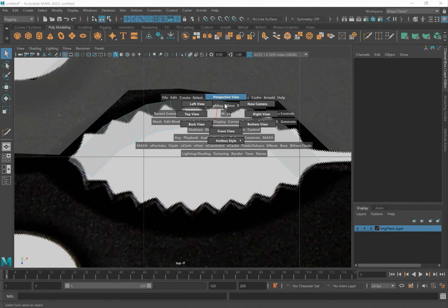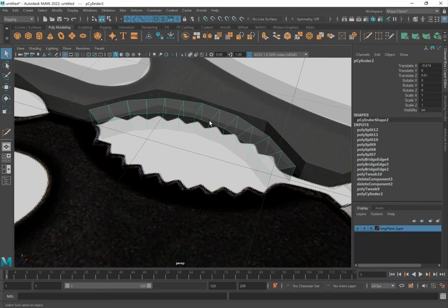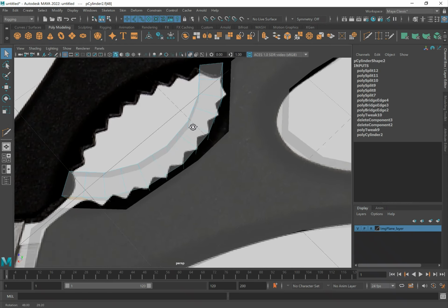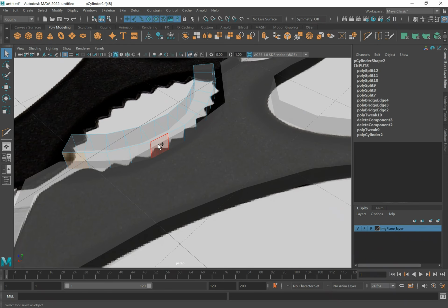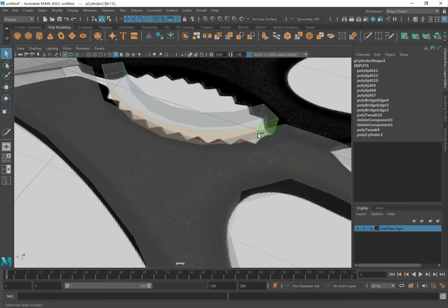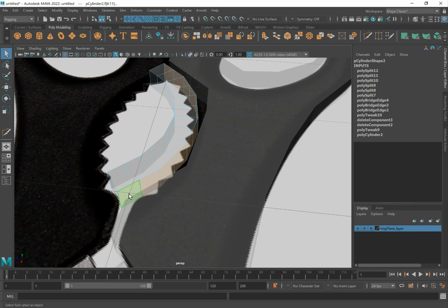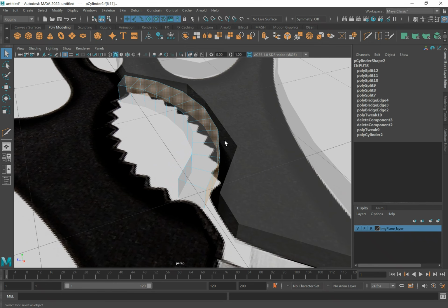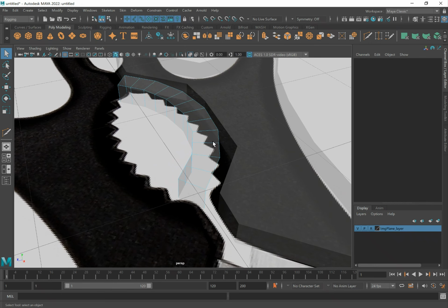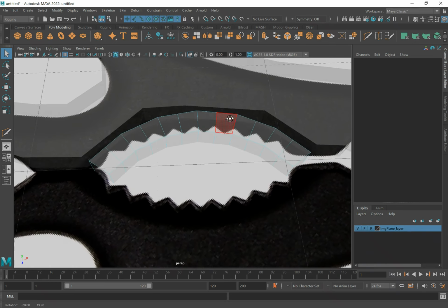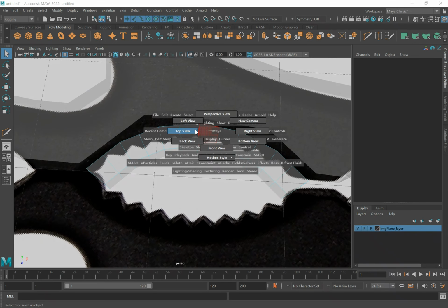Next thing that I will want to do is select the faces behind. I'm going to shift double click, and then shift double click again, and then here. Because if I were to shift double click at the end in one stroke, sometimes it may not do the right selection. I'm going to remove the back faces because eventually this is going to be merged to this surface there.